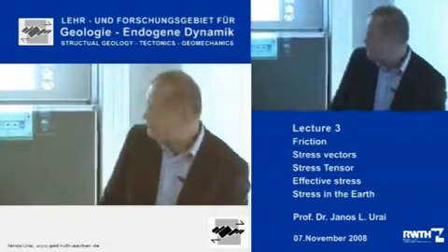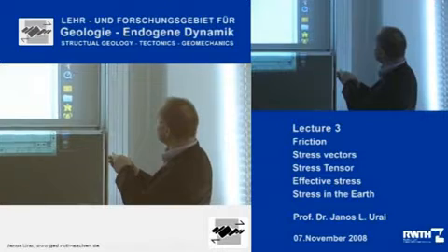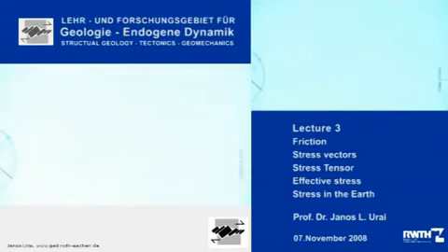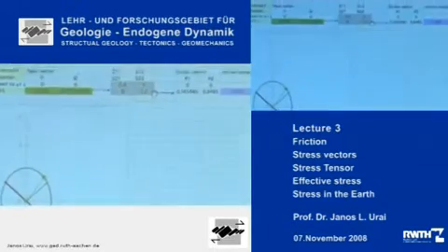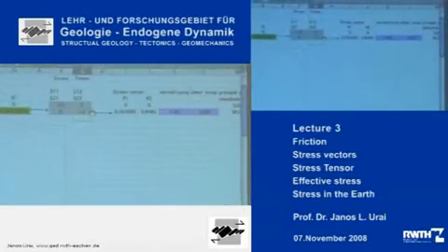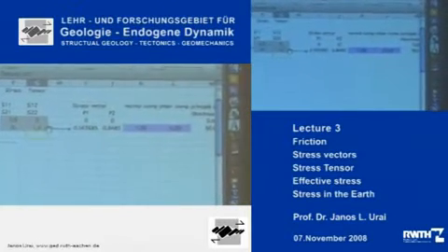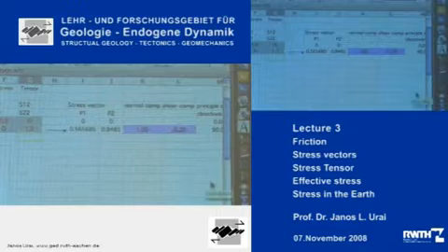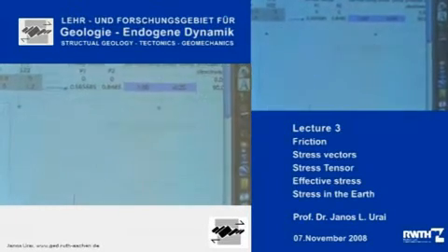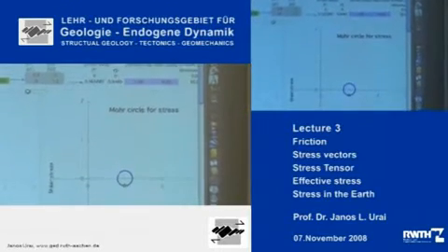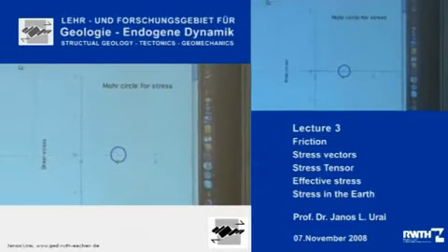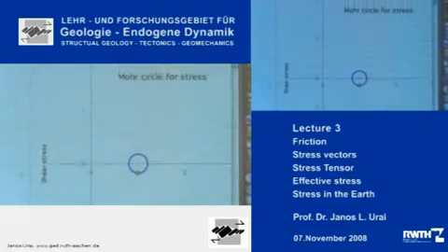Now what I've done here is I calculated the normal component and the shear component of my stress vector. These two numbers are the coordinates of my stress vector on the plane. And then what I've done is I've plotted this normal component and shear component against each other. And I've opened this figure now. Here it is. The shear component is this much. The normal component is this much. This is my plane. In the new diagram, it is a point.